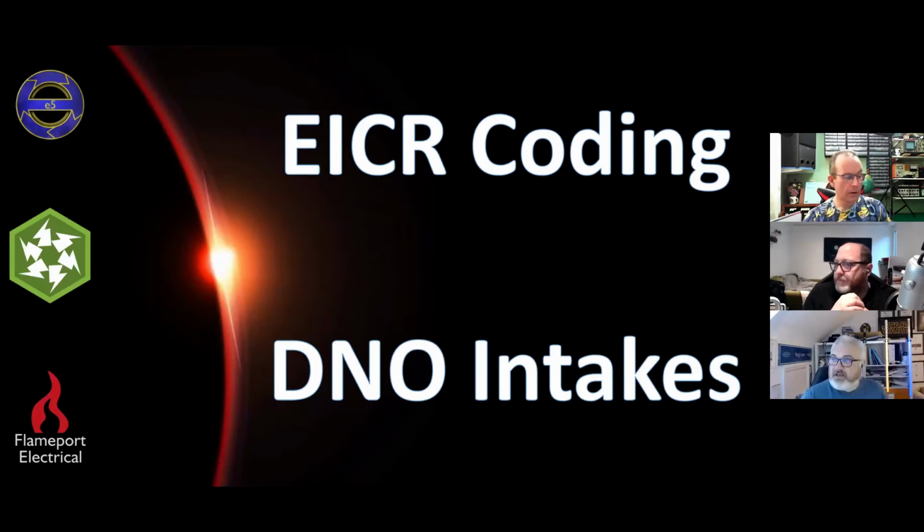Right, so today we're going to cover DNO intakes. The reason we're covering DNO intakes is, as you'll see today, too many of them. We go into too many installations and we are trying to spend a lot of time figuring out what the supply configuration is. Now, I'm going to put my hand up and say 20 years ago, when I was doing it every single day, it was very simple to spot a TN-C-S, a TN-S, and a TT. Well, with TTs you had to find the rod, but it was pretty simple to identify a supply type. Now it would appear that it's getting far more difficult, and we're getting lots of weird, funny configurations.